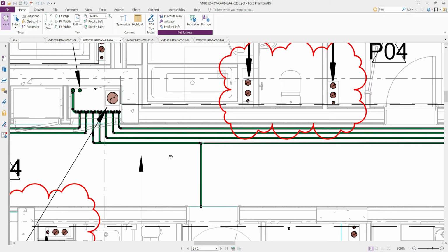I need to place 5 pipes. I'm gonna keep 100 mm distance from the wall to the pipe's insulation, and I've also been told to keep 40 mm between the pipe's insulation. As well as that, I need to keep 50 mm between the underside of the slab and pipe's insulation.